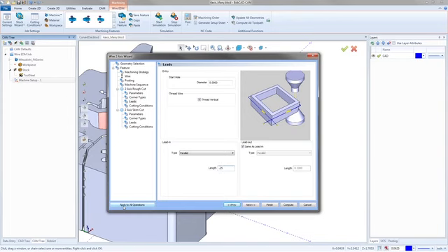If you look in that bottom left-hand corner, there's that button for Apply to All Operations. You can take anything on this page, apply it to all operations, and then any other leads page in this tree on the left is going to copy and match those leads. You do have to make sure it works for every single cut, because a parallel lead-in might not work when you're doing your tab cut. If you did this with a tab cut set up, you'd have a parallel tab. So you may have to play around with some of the settings there. Right here, we go next.